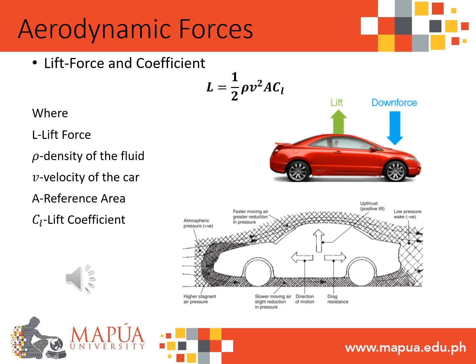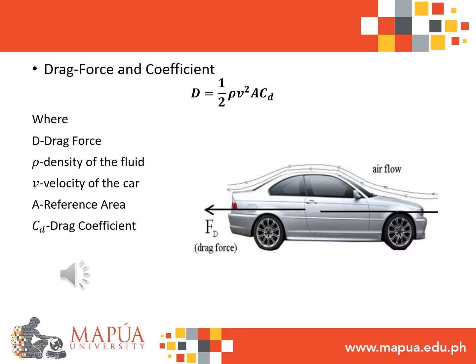The lift force depends on the density of the fluid, velocity, viscosity, compressibility, and the surface area of the object where the air flows over. The shape of the object and its inclination also influence the amount of lift force to be generated. In aerodynamics, the lift coefficient is a dimensionless number or parameter that takes shape, inclination, and some flow conditions into consideration. The coefficient can also be expressed as the ratio of the lift force to the force created by the dynamic pressure times the area.